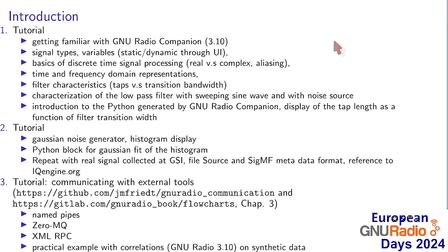In the first tutorial, we got familiar with the GNU Radio Companion interface. We've seen how to handle real quantities and imaginary quantities, addressing such awkward values as negative frequency and imaginary voltages. We characterized the properties of a low-pass filter, and we showed how we could introduce our own Python code in the generated GNU Radio Companion Python program. However, we emphasized that the Python code could only interact with scheduling and the connection of the various blocks, and not with the IQ stream.